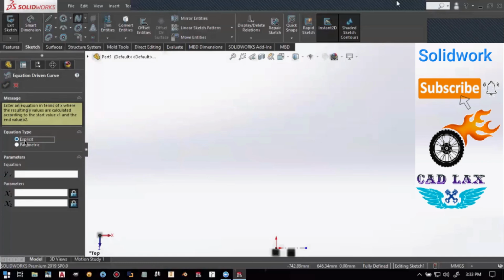If I take explicit and put in an equation, for example a simple equation like sin x, in place of theta we have to take x. So sin x. Now we have to specify the value of x from x1 to x2. These are the limits. If I take 0 to 10, let's see what is created.